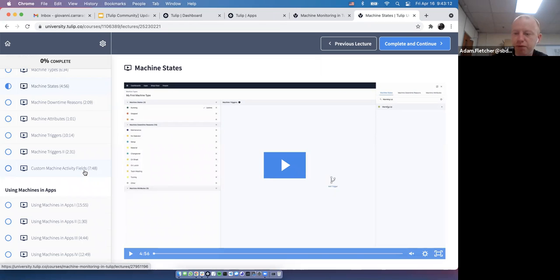Now, if you did it before it chipped, you only need to do one regrind, and then you've got like 75,000 tool uses. But you can only do that 5 times before there's no more tool left. Whereas if it's chipped, you have to take off it twice or 3 times. So you're saving a couple of 100,000 parts that can be made by that tool. You save on the tool usage, the regrinding, and the scrap: everything that had been made with that tool when it was chipped goes in the bin.